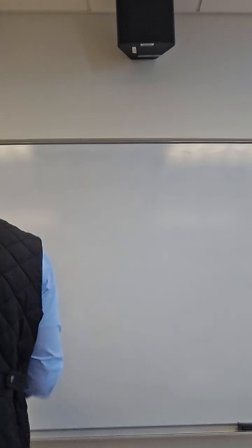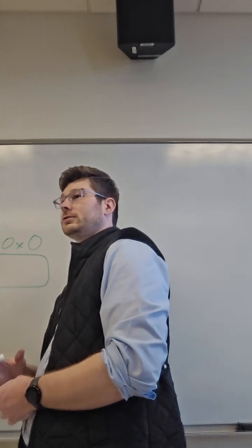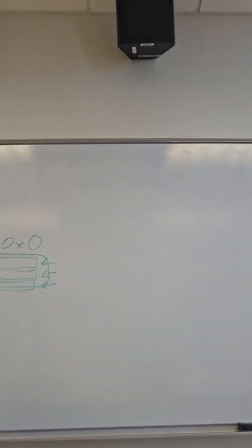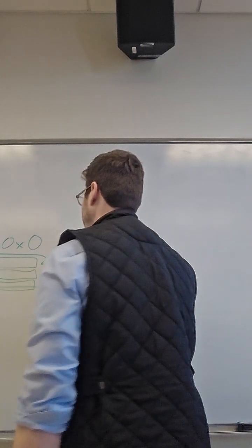When I was talking about that it's a book, inside of our device, a device might be address 0x0, the 0th device, the first address on the bus. And then that address will have even more addresses, more slots for data to go. Each of these data slots can hold some amount of information. Here this is 8 bits. So that's pretty much one number you could put in there.